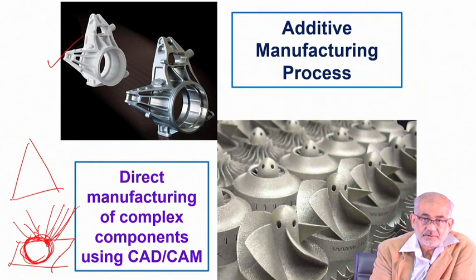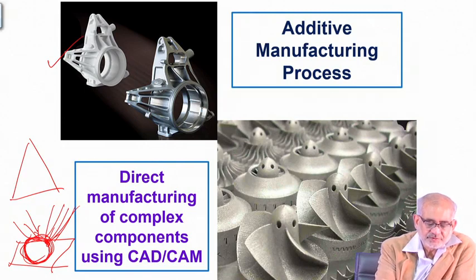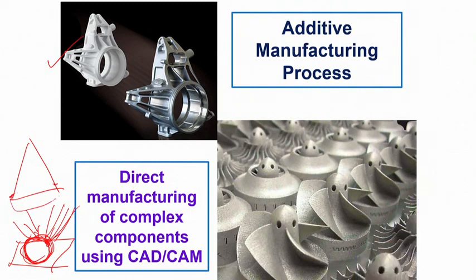of a particular powder coming from top. And of course, I have my ability to control not only the precise diameter or the shape, circular shape, but also the height of the shape. So I build up, in the first layer, only up to this depth. So this is one circular section that I have created. The next time I reduce the diameter, I describe a smaller diameter circle. And so now I create another one which is shorter.